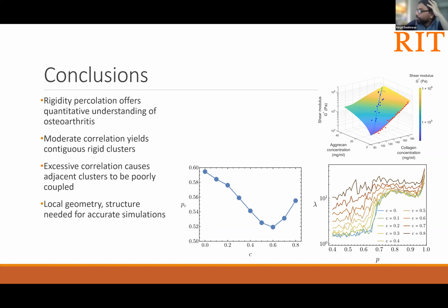So I can start. I suppose you're always below the Maxwell threshold, which is 4 in 2 dimensions in your simulations. And so I expect the shear modulus is dominated by the bending, and so by the bending modulus. So is that something you can vary in experiments, such as by varying collagen cross-linking? Like, can the bending modulus of the collagen fibers be varied? And have you looked at the effect of changing the bending modulus parameter in your simulations?